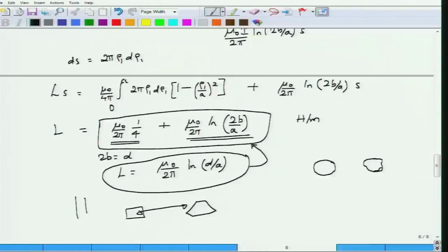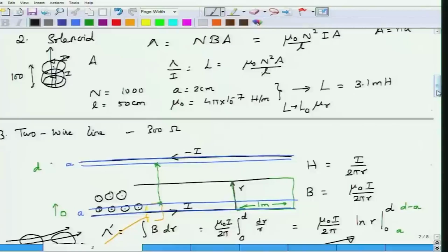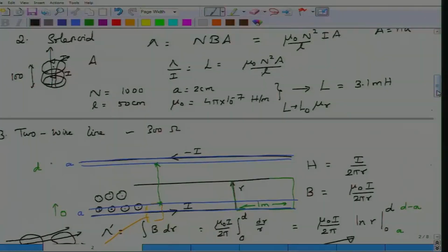There you will calculate magnetic field numerically, and from there calculate inductance numerically, okay. However, you have to understand where one can put in some approximations to quickly obtain a value for inductance, and then if you want quantitatively better answers, you have to employ numerical methods or solve the complete electromagnetic problem.